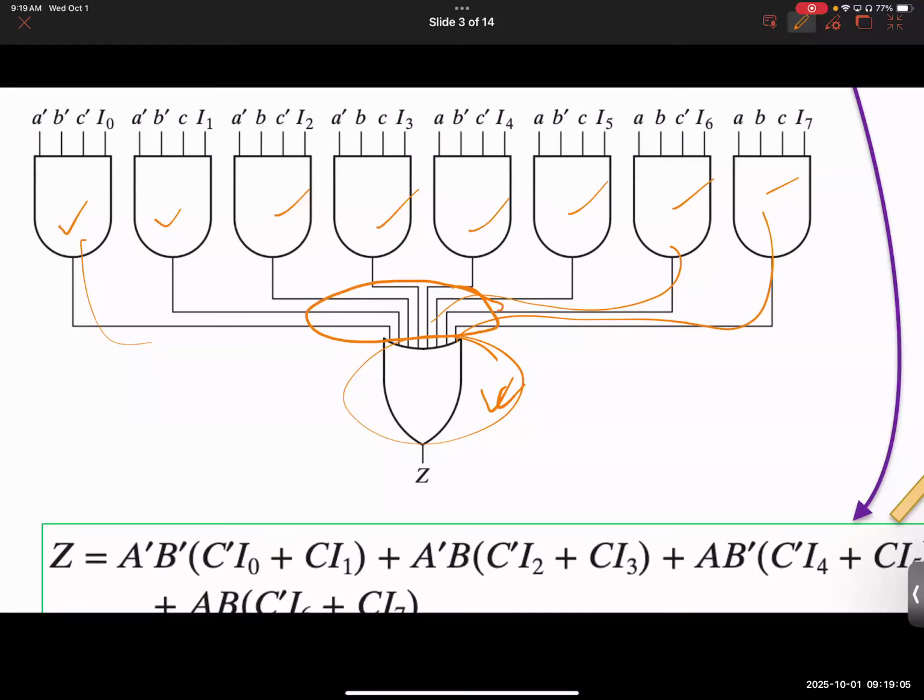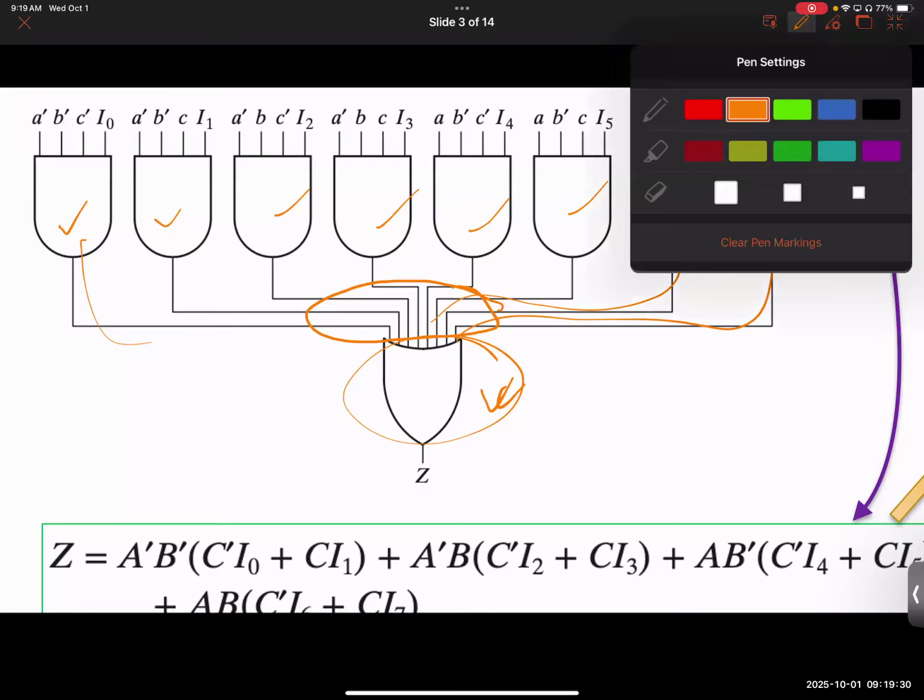And if you want to get a number in your mind, typically fan-in beyond 4 is challenging to handle. Just keep that in mind. 4 is kind of like the sweet spot. Anything less than that is probably an overkill. Anything more than 4 will lead to performance degradation. So it's kind of like an optimization problem. It cannot be too high or too low. So 4 is typically the sweet spot. Just keep that in mind.